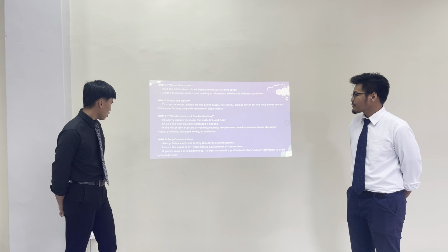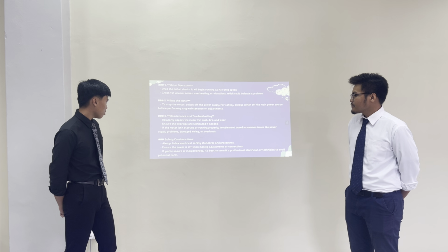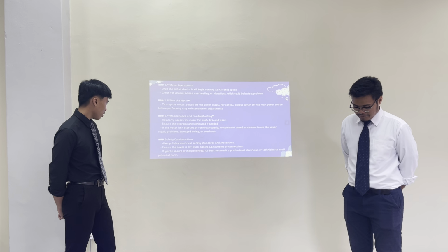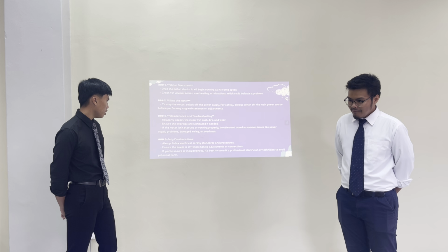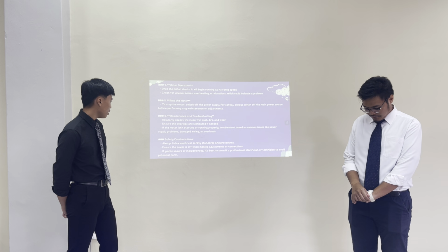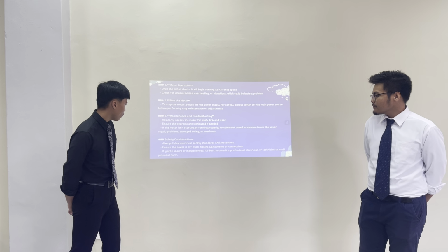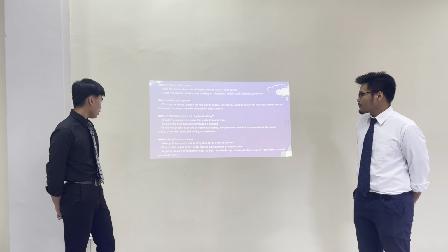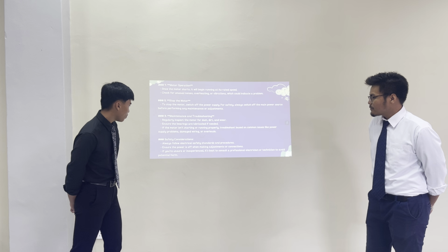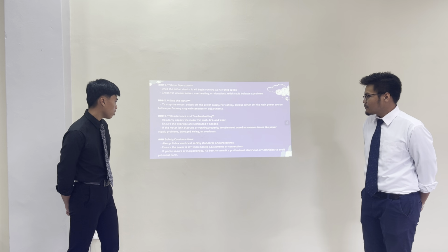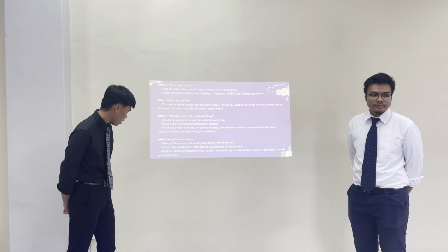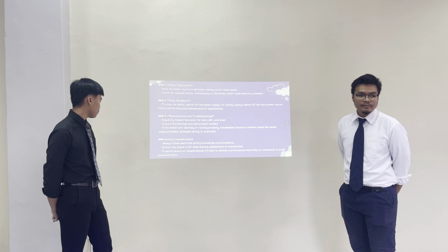9. Maintenance and troubleshooting. Regularly inspect the motor for dust, wear and tear. Ensure the bearings are lubricated if needed. If the motor is not starting or running properly, troubleshoot based on common issues like power supply problems, damaged wiring, or overload.